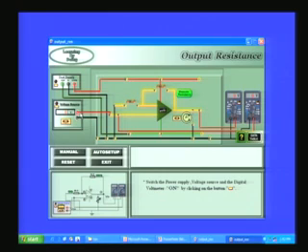And the voltage from the voltage source is connected to the non-inverting input here, and therefore, it is a non-inverting amplifier with a gain 1 plus RF by RI, and the RF by RI is equal to 1 here. Therefore, it is a gain of 2. 1 plus 1, 2, is the gain of this amplifier. And now, what I do is I always have large resistance here. This is a potentiometer, and this is having very large resistance.